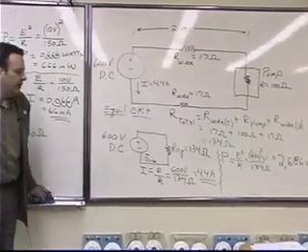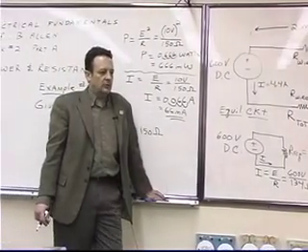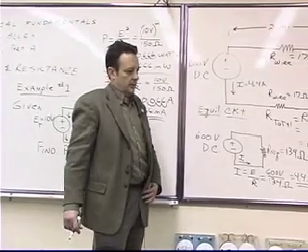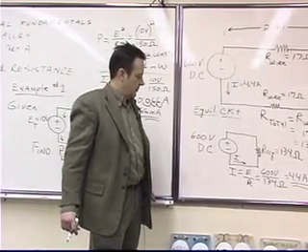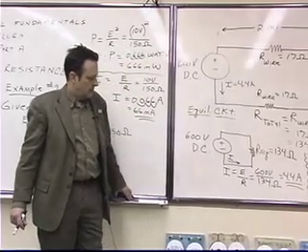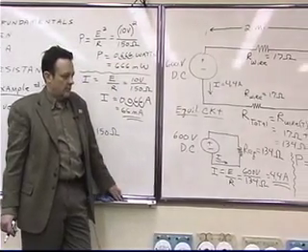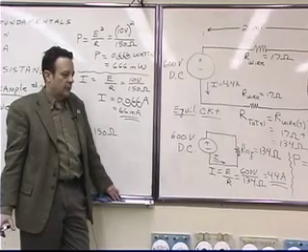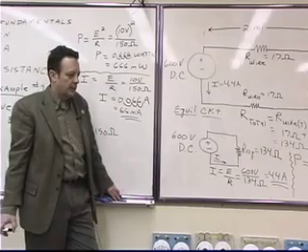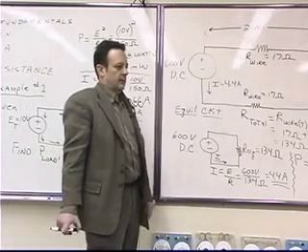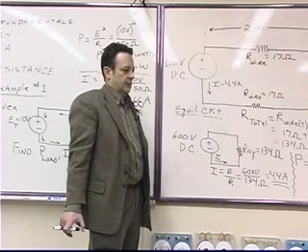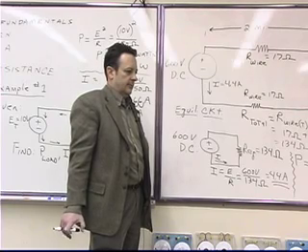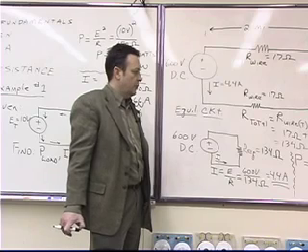Now, is that a valid method? Is that a formula in the Ohm's law wheel? Yeah, but you get a different answer if you multiply amps times volts. E times I equals VA. Okay. So we're talking about apparent power. E times I. Yeah, that's what it says here on the wheel. You get a different answer. It's off by about 40 when you do it that way. It's off by 40 watts.